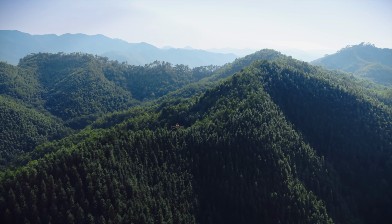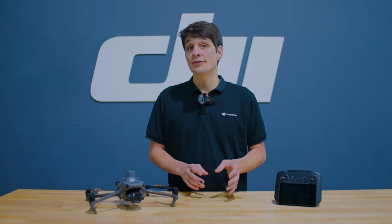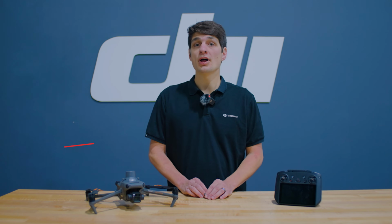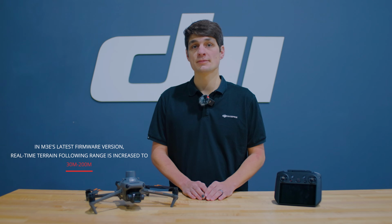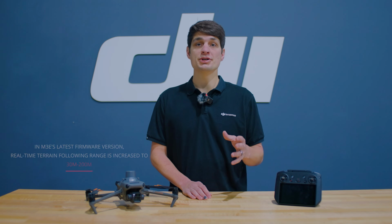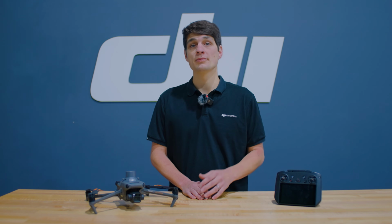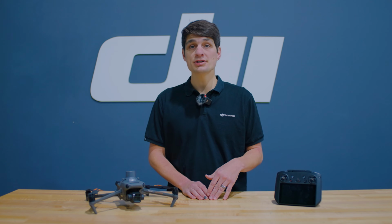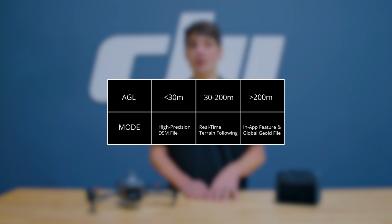There are a couple key points on real-time terrain following that you'll need to take note of. First, real-time terrain following currently supports flights from 80 to 200 meters. If flying over 200 meters, it is recommended to use the new in-app feature to download the global geoid file. But for flights below 80 meters, it is recommended to import a high-precision DSM file which can be generated by DJI Terra after one flight mission.